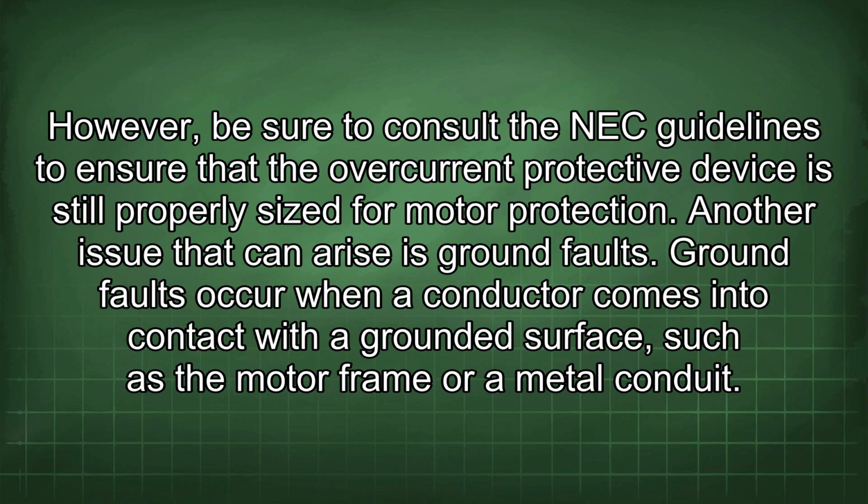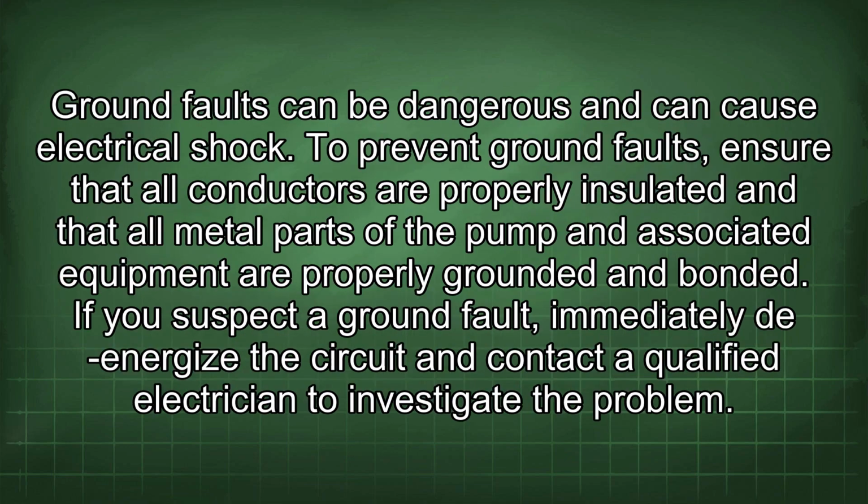Ground faults occur when a conductor comes into contact with a grounded surface such as the motor frame or a metal conduit. Ground faults can be dangerous and can cause electrical shock. To prevent ground faults, ensure that all conductors are properly insulated and that all metal parts of the pump and associated equipment are properly grounded and bonded. If you suspect a ground fault, immediately de-energize the circuit and contact a qualified electrician to investigate the problem.